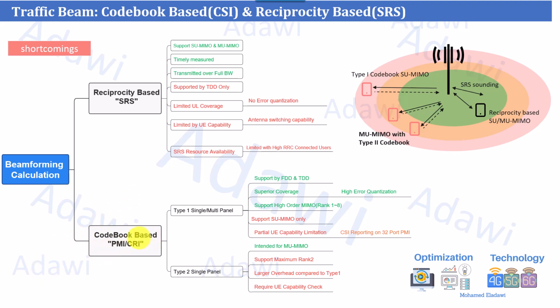Codebook-based means that the gNB itself will apply a precoding matrix to maximize the signal-to-noise ratio, so it will identify a vector of codes which will be transmitted and carried on the so-called CSI-RS whenever the gNB is transmitting the CSI-RS in the downlink direction, and the user will be able to decode the best precoding matrix and report it back to the gNB in the uplink direction to tell it, this is my location, I need this particular beam.